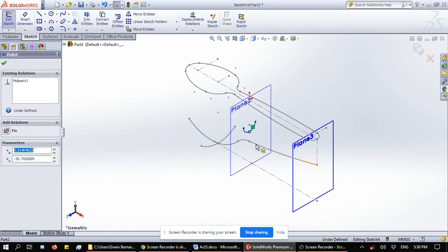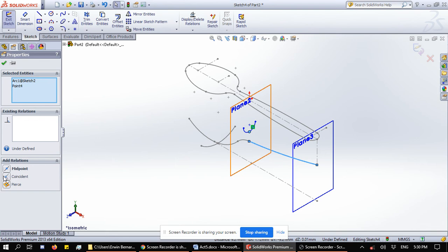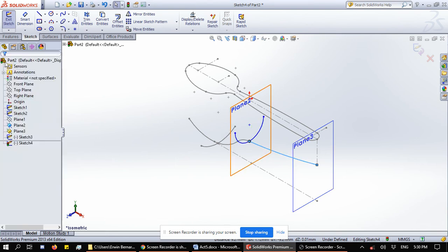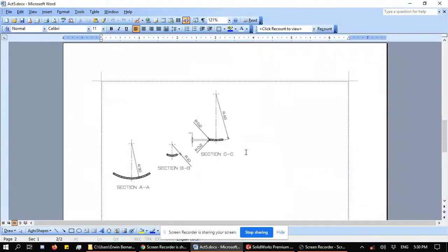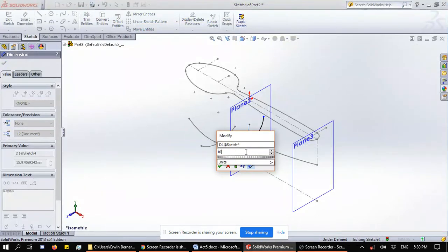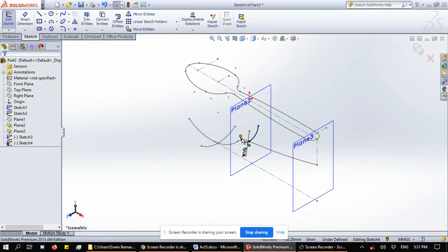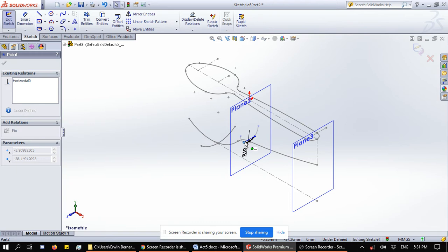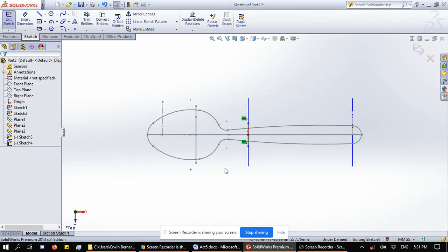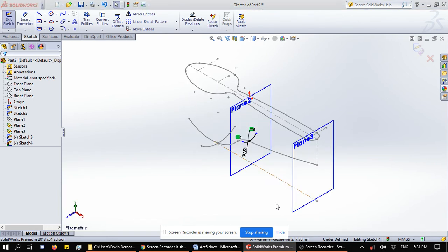Select the point and the body, and we pierce it. After piercing it, as I mentioned, it needs to have a radius of 10, if I'm not mistaken. And we retract it a little bit. Up view to check it. Okay. And we can exit sketch.